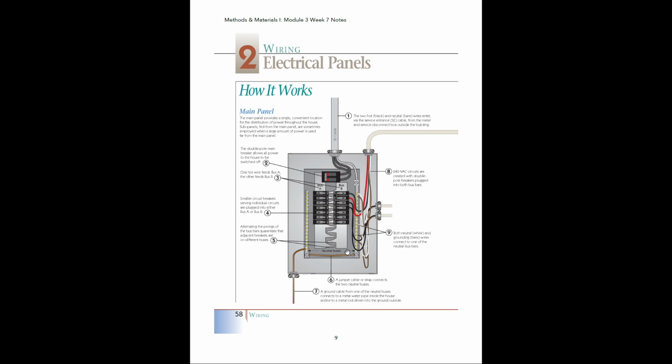And like I said, if there was some sort of an accident where somebody's going to be electrocuted or something like that, the grounding mechanism is going to carry that dangerous voltage back through the wire down here into this bus. It's going to run along here to this jumper cable at the bottom. That's going to find its way through this ground wire here, downward, and this then is going to be connected to your main water line, okay, for safety reasons.